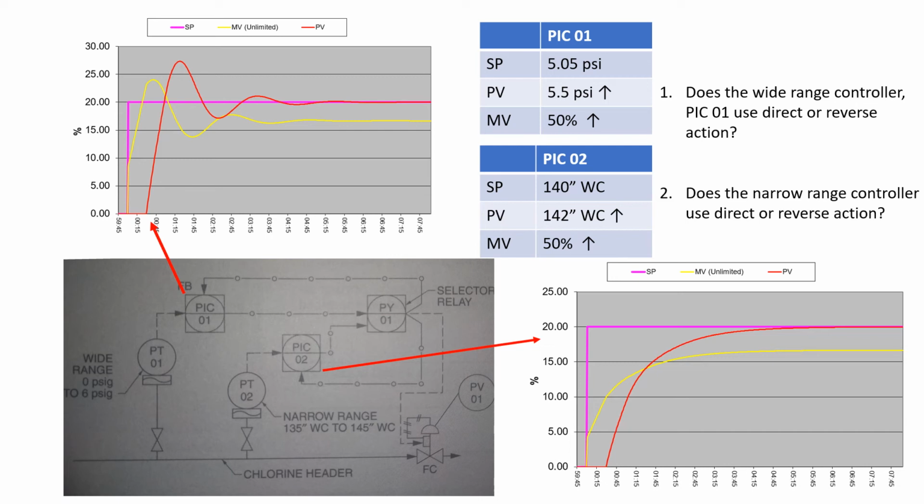And this matters based on where the transmitter is in relation to the valve. We want this valve to open more and let more material go out. It's fail close, so air to open, so we want to open more so that we can control this and relieve that pressure. So that's a direct acting controller. Now, it's pressure. This is still before the valve, so PIC02 is the same thing.